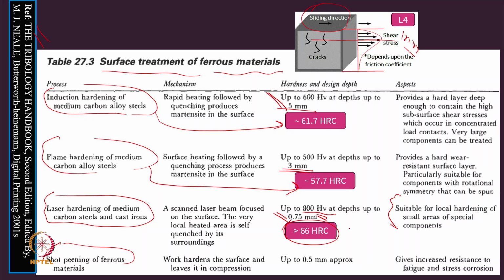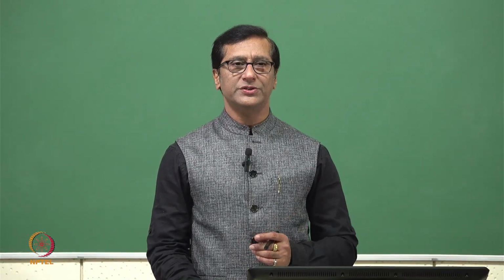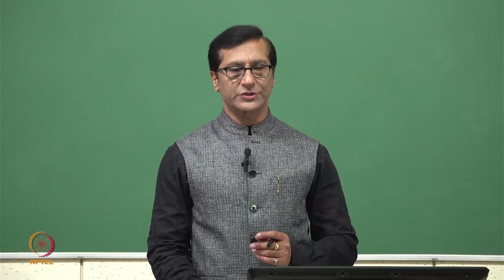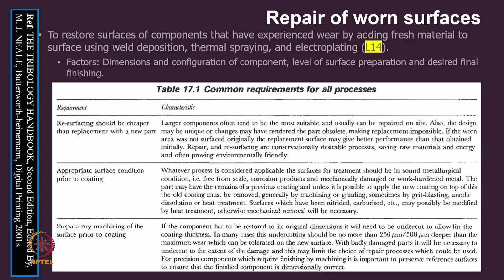However, if the surface texturing is more important, and it is possible up to 500 micron, we can go ahead with shot peening, because for most of the materials, as a finishing operation, shot peening is done on the surfaces also. So the localized heat treatment with the texturing happens on the surface, and that is the work hardening of the surfaces because of the shot peening method.